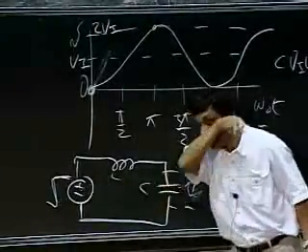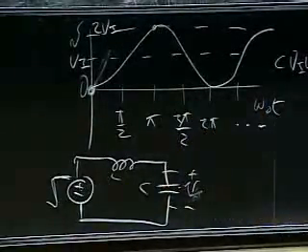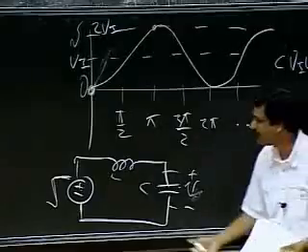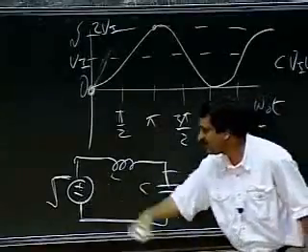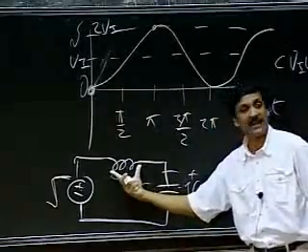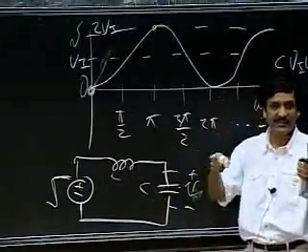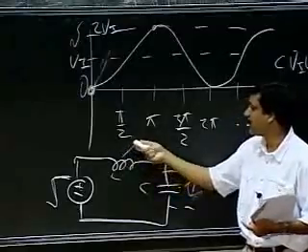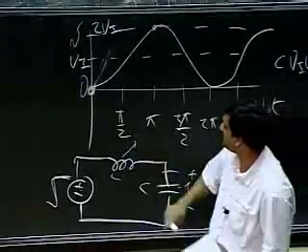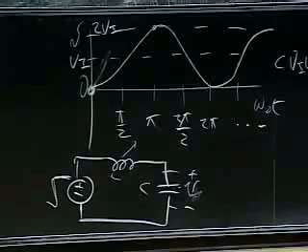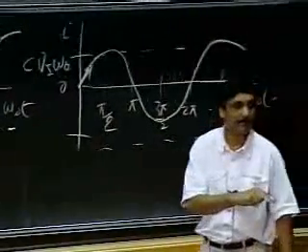Okay, so the entire voltage here, KVL must be true no matter what. The absolute fundamental principles from Maxwell's equations. So KVL must hold, which means that the entire voltage VI must appear across the inductor. So I put a big voltage across the inductor, and its current begins to build up.